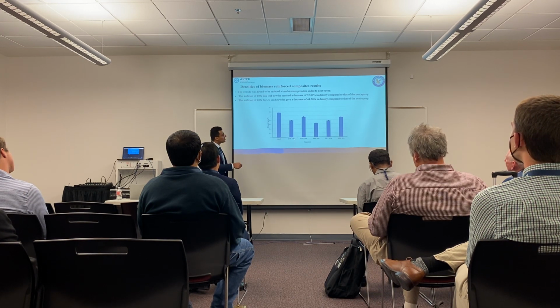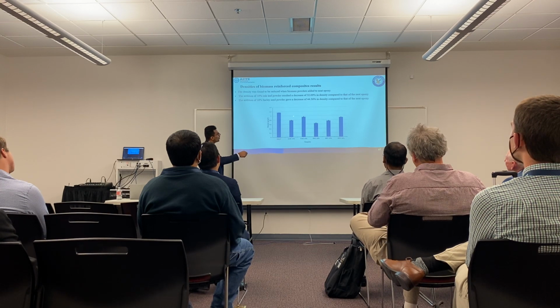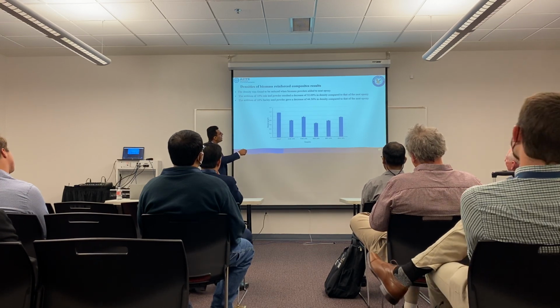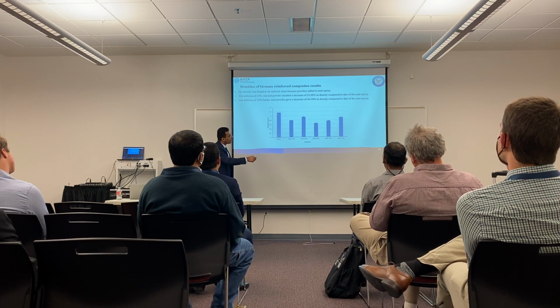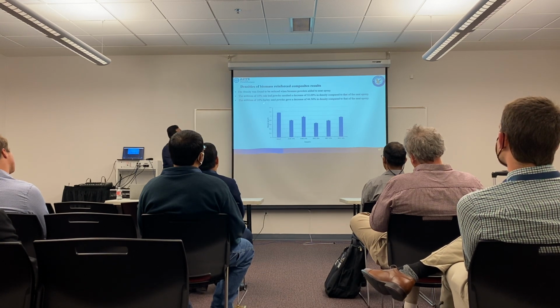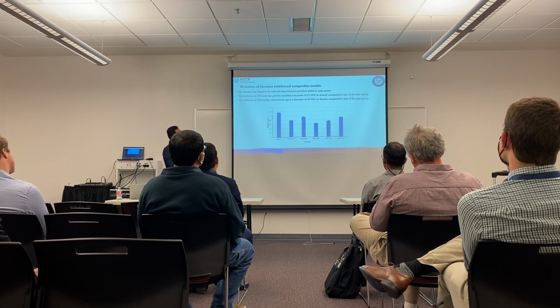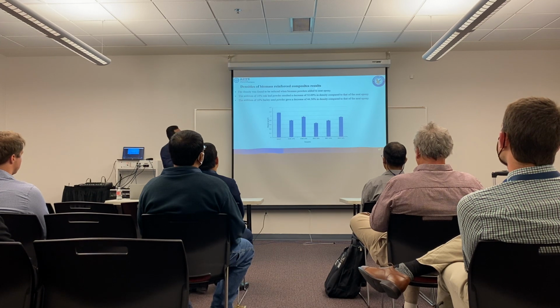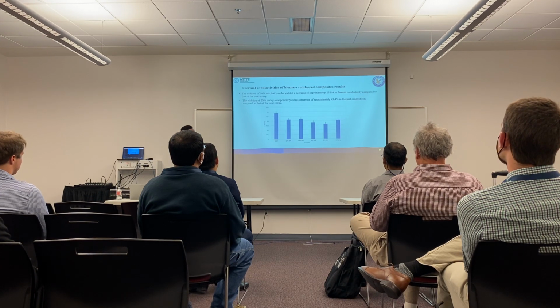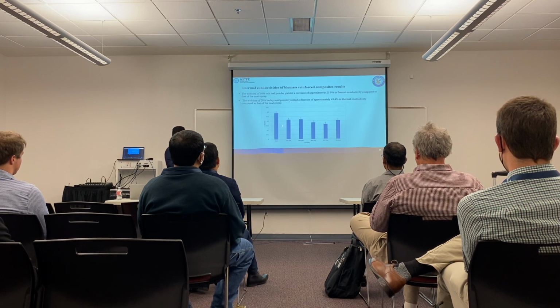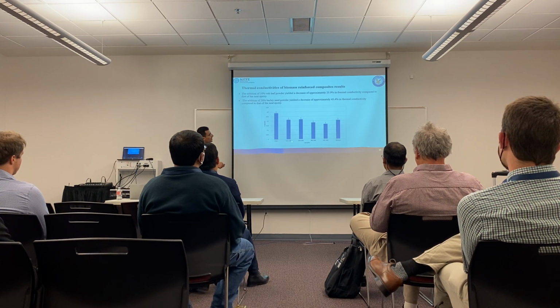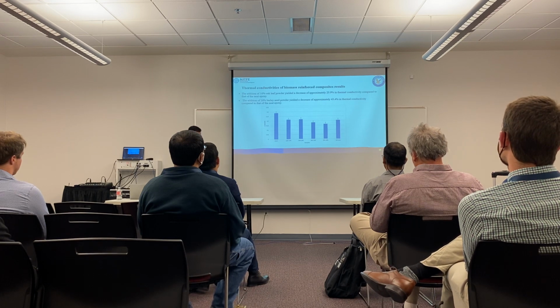We added 10% and 20%, and we compared this neat with the lowest amount of oak leaf, and we compared this with our amount of barley seed. For example, here density was found to be reduced with the biomass powders added to the neat epoxy, and the same with the thermal conductivity. This is neat with the 10% and with the 20% of barley seeds.